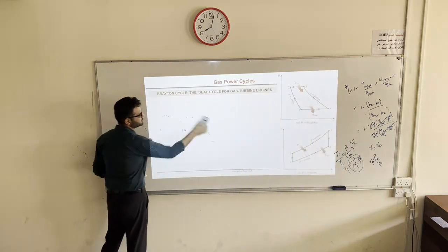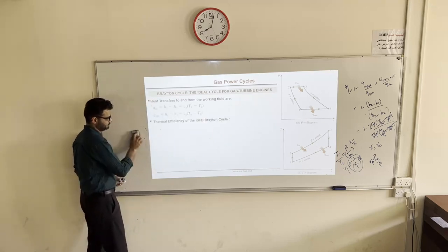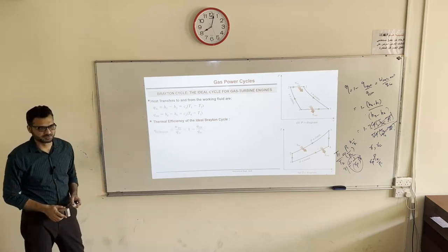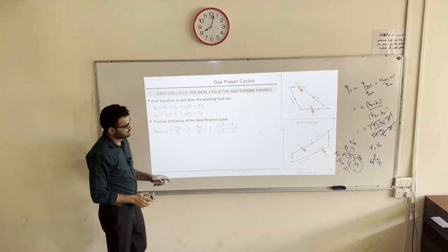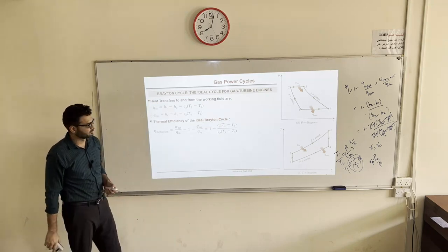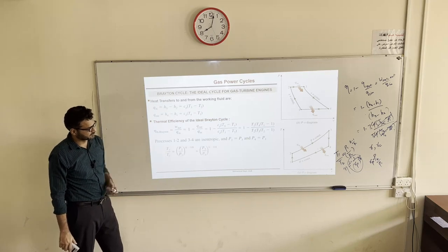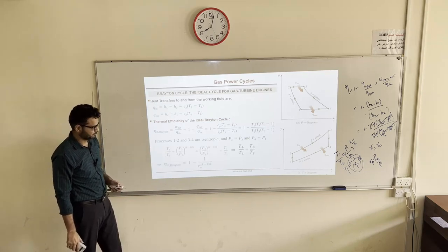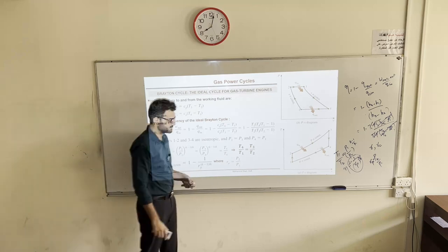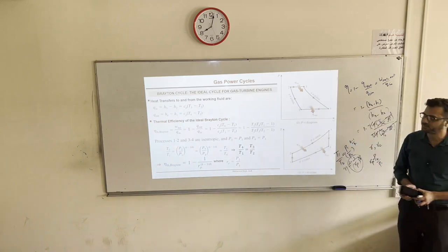So this is done here on this slide already. Q in, Q out, efficiency. Here again, the major assumption is we are assuming constant specific heat. So this is clear. Efficiency is a function of pressure ratio and specific heat ratio.